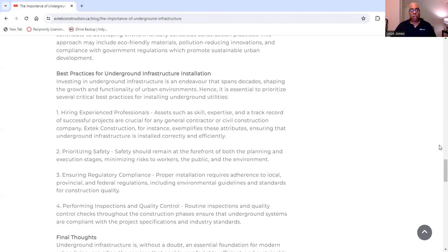That's number two. And number three, because we are dealing with the underground, you have to be careful that when you're excavating and you're going to put in brand new infrastructure, watch out for underground storage tanks. You could have contaminated soil. And when you have contaminated soil, that soil must be removed from the site. And when it's removed from the site, they're going to run it through a dryer to make sure they get the contamination out. Now, you may not be able to use that soil again.